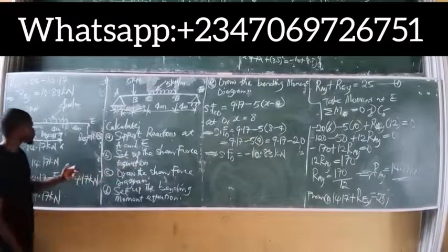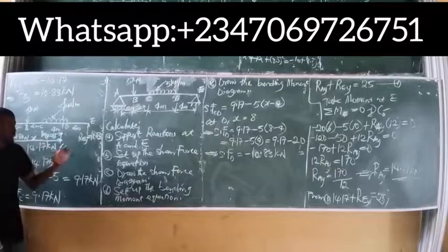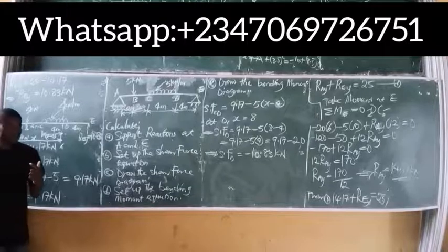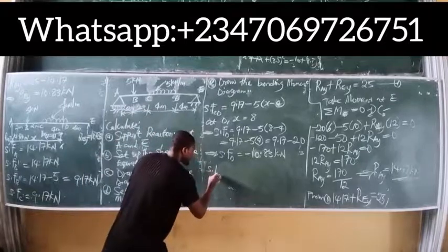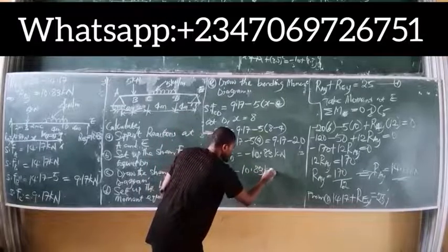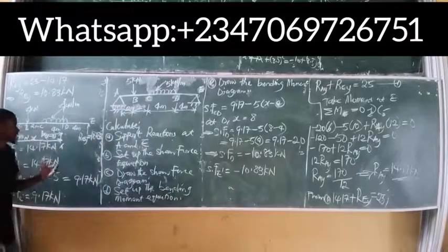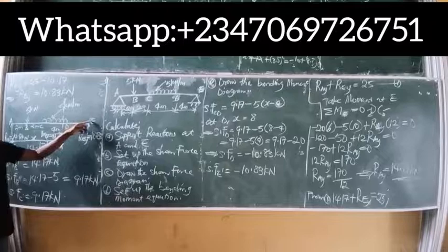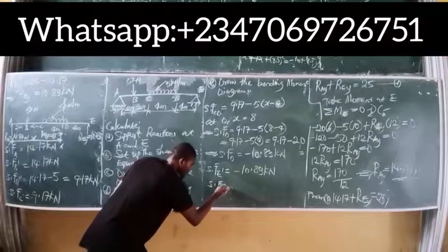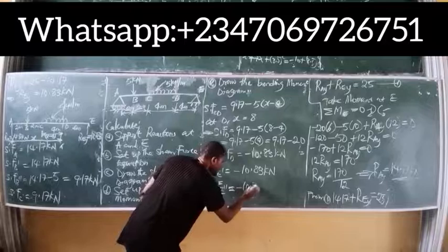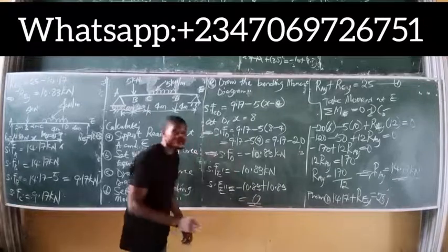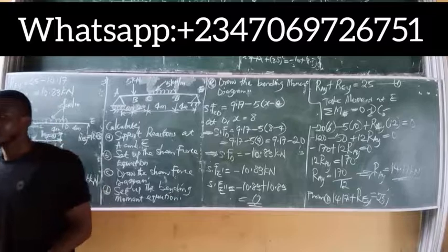So this same force moves from point D down to point E. But because I have the force at point E, I will call this shear force E prime, which is initially at point E. So this same force moves, and we have minus 10.83 kilonewtons. But on getting to point E, it realizes that I have an upward force at that point, and that force is positive. So finally at point E, the shear force E prime prime is equal to minus 10.83 plus 10.83. And the value is simply 0. At the end of every shear force analysis, you must obtain 0 as the answer.